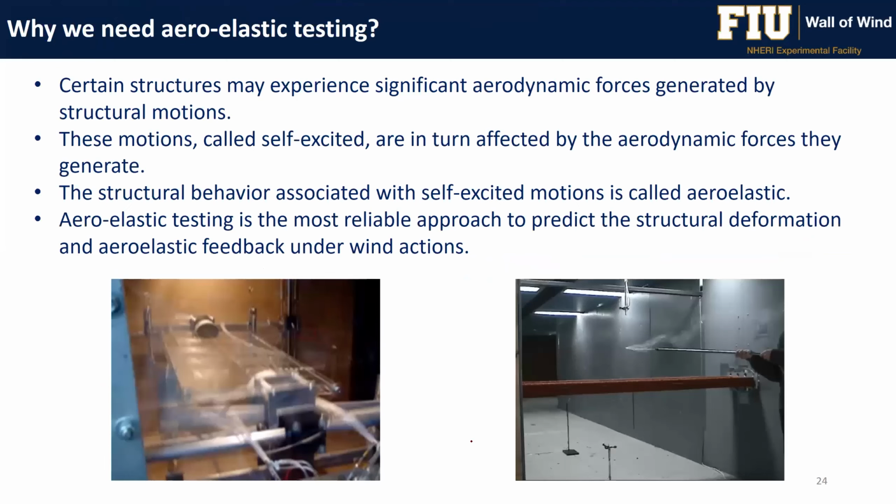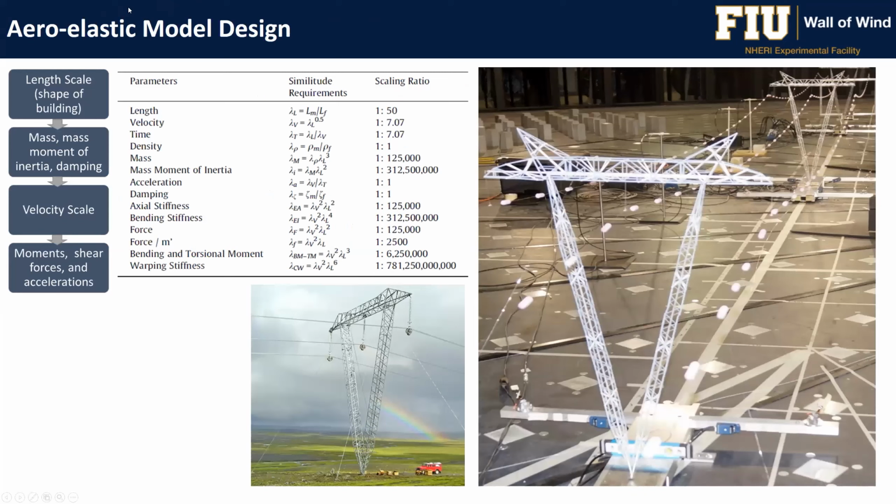Perfect. So the fourth type of testing that we do is the aeroelastic test. It's more complicated because we need to replicate the dynamic properties or the motion of the structure under wind excitation. Certain structures will experience significant